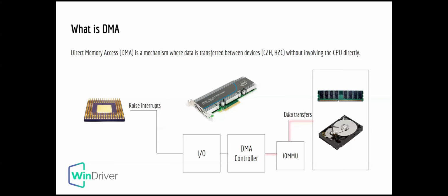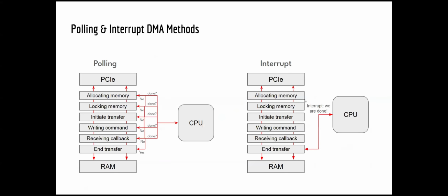So we said this is DMA, and there are different types and methods to perform DMA. We want to keep the CPU as much as we can out of this operation, for both a faster transfer and to reduce the occupancy of the CPU.